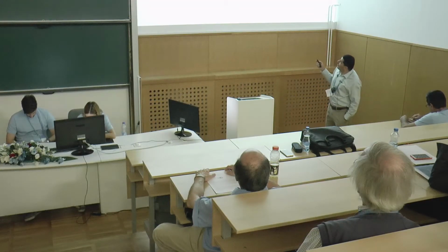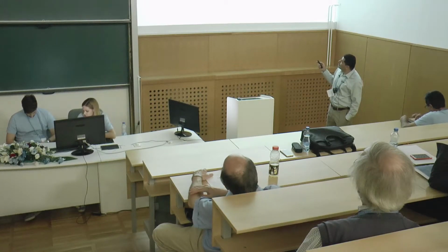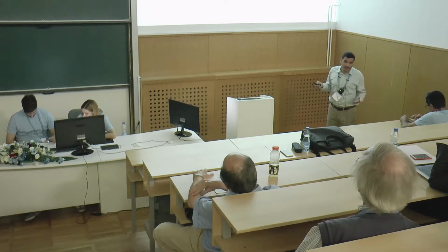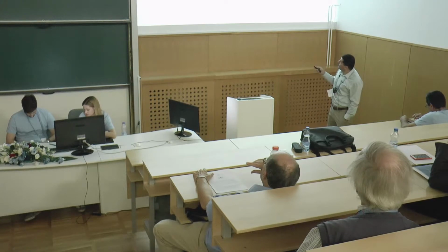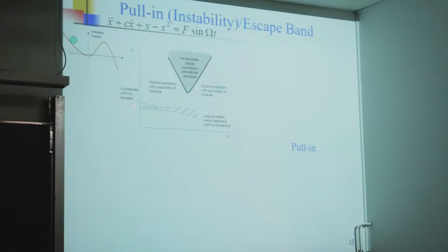If you have this spring mass system, then you can characterize the kind of bifurcation the system will experience as a function of the frequency and the forcing. So in this map, for a forcing below this line, the system is linear. There is nothing strange. Above this line, you start to have hysteresis and softening or hardening. Then as we climb up, the basin of attraction for the system becomes weaker.